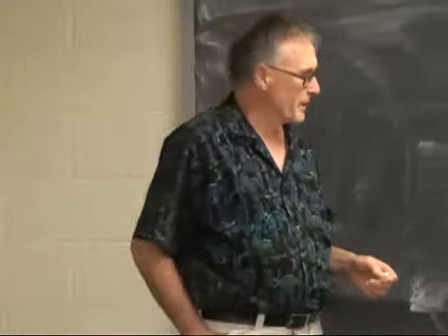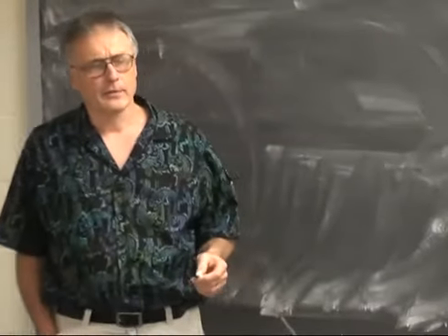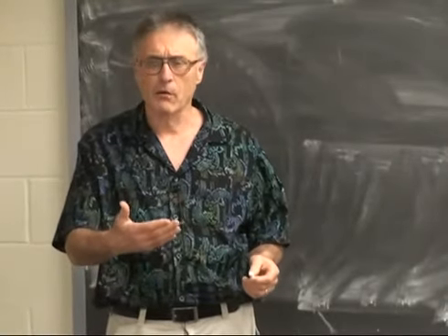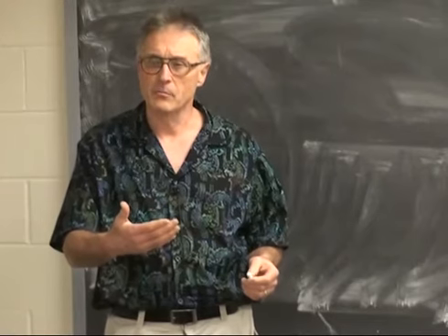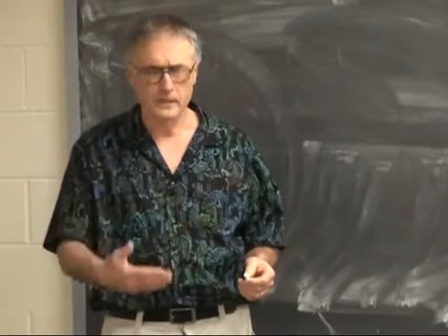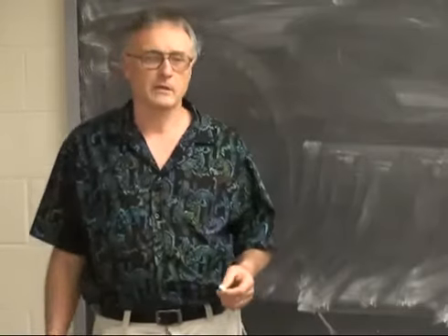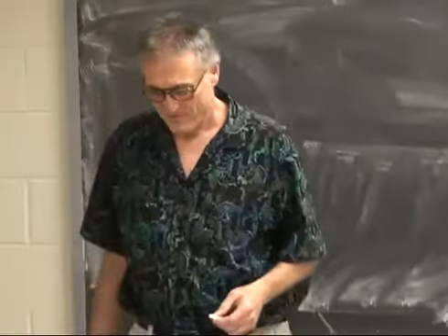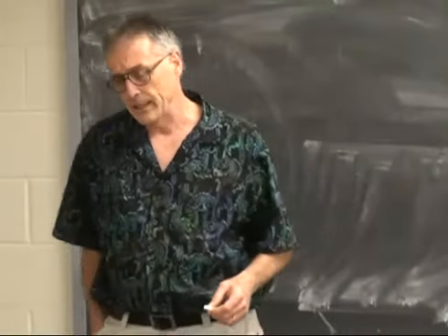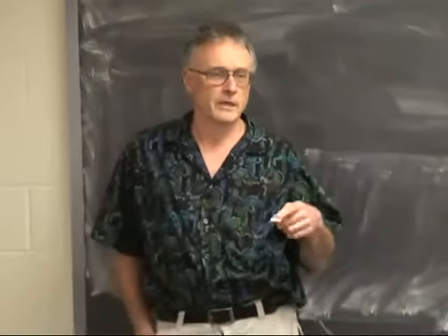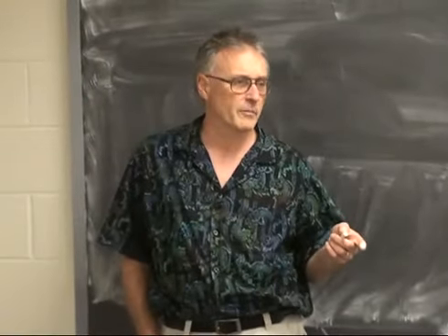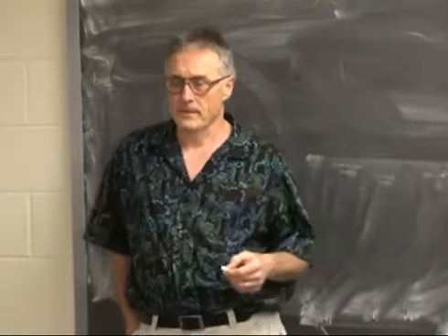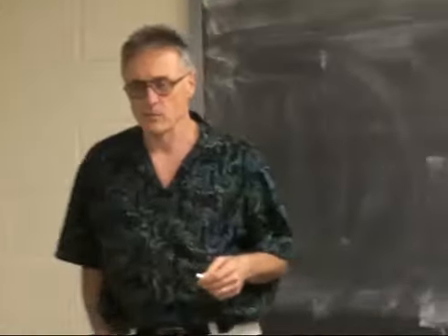I've had a couple of times when I built Nios systems and compiled them, and it didn't use any space at all for the Nios blocks. There was zero size for the design, because I forgot to connect the clock. So it's not a bad idea to cross-check by looking at the size of the design after the compilation and make sure that it's about the size you expect, because that'll tell you if something's been optimized away.